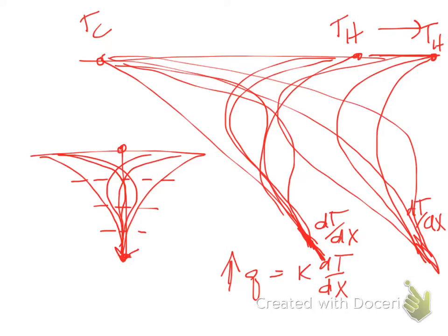The e-folding time, or our tau, the Maxwell time constant, and how we said that 5 of those gets us most of the way to where we want to be. That's true of most e-folding processes. The outer envelope that this falls into for the steady state solution is an exponential curve. There's all sorts of other things going on inside there, but the outer envelope is an exponential, and so we can do the same thing where we call this a skin depth.